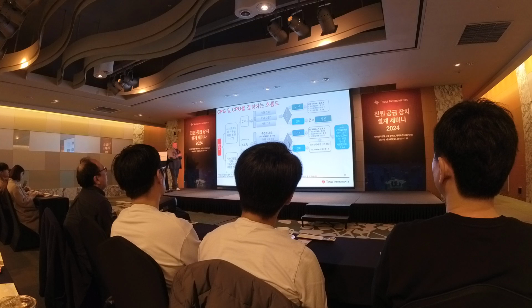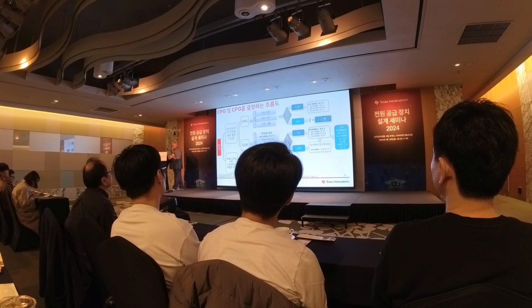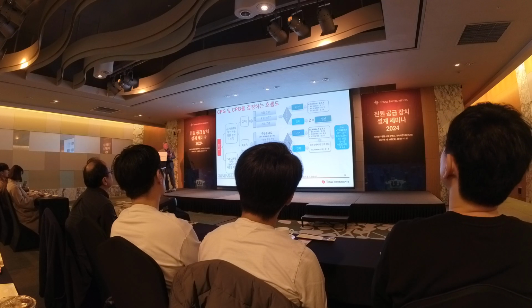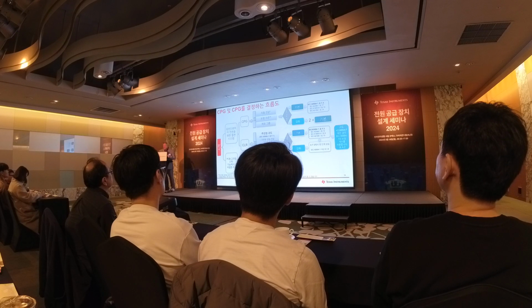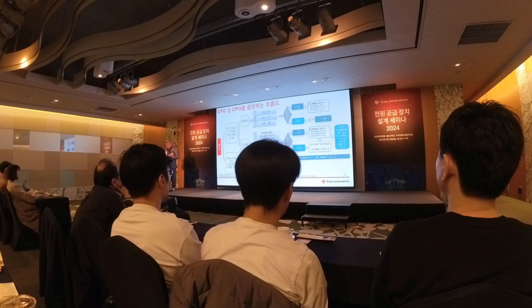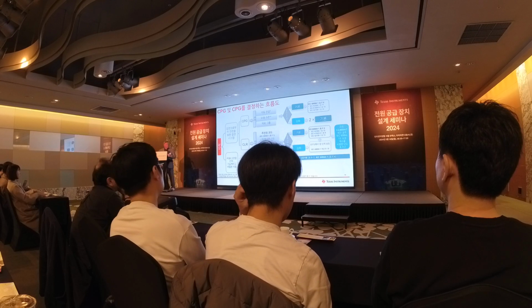If my PCB doesn't need safety, creepage, and clearance, then I can use high voltage spacing, and there are a few different parameters that I can look at. So I can look at the general PCB guideline, and that's IPC 2221B.